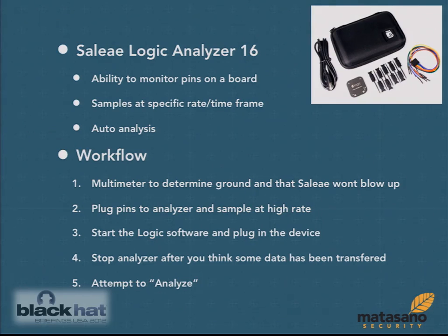So the workflow that I was going to use in order to determine what data was going over this was first to use a multimeter to make sure that once I plug my logic analyzer into this, it's not going to blow up. It's not sending a huge high signal that's going to cause the thing to fail. From there, I was going to plug the logic analyzer into the pins, start the logic software, which runs on your computer, and then plug the device in. When I think data has been transmitted, stop the logic software, and then try to analyze it with the preset analyzers that they have built into the logic software.